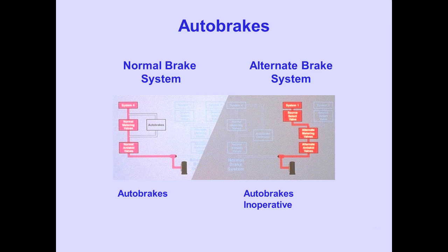Recall, auto brakes are powered only from the normal brake system. When the alternate brake system is activated, auto brakes are inoperative.